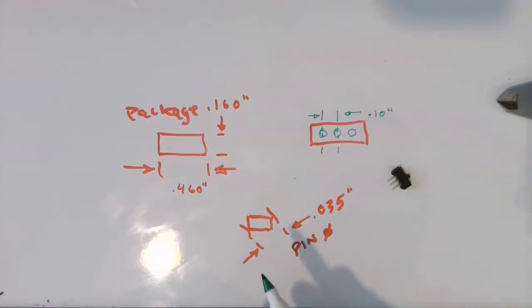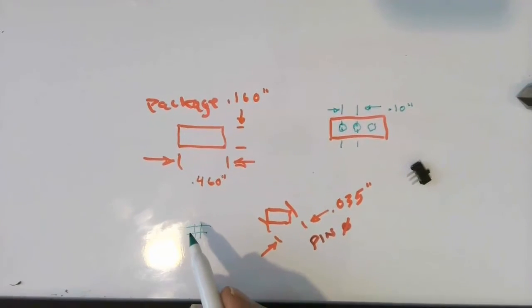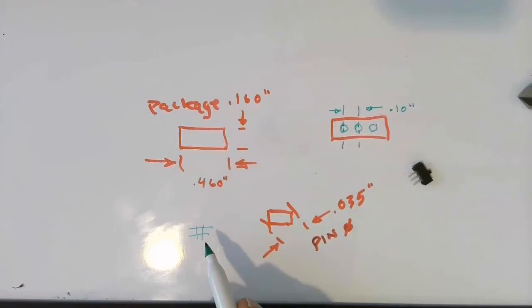But when we start talking about PCB manufacturing processes, what we'll find out is that for some of the processes it's subtractive, where we etch the material, but then in some cases we're adding electroplating parts. And so what happens is that the actual hole diameter that's drilled on a circuit board, if we had the PCB material and we drilled a hole, what happens is that that hole ends up getting plated on the inside. And that might be a couple thousandths of an inch.